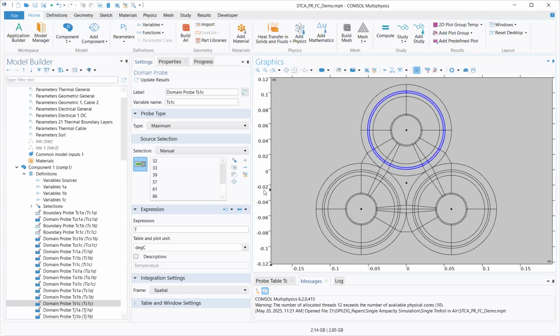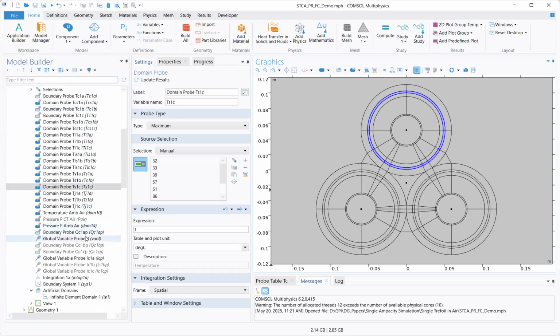we can see the results live as the simulation is running. We can see those values, and if we see something doesn't make sense, we can stop the simulation before letting it run for whatever time it takes to finish, right? We could immediately detect something's wrong, stop it, fix it, and then continue. And then once we see that things look good, we let the simulation run. We let it finish. And then we could also apply